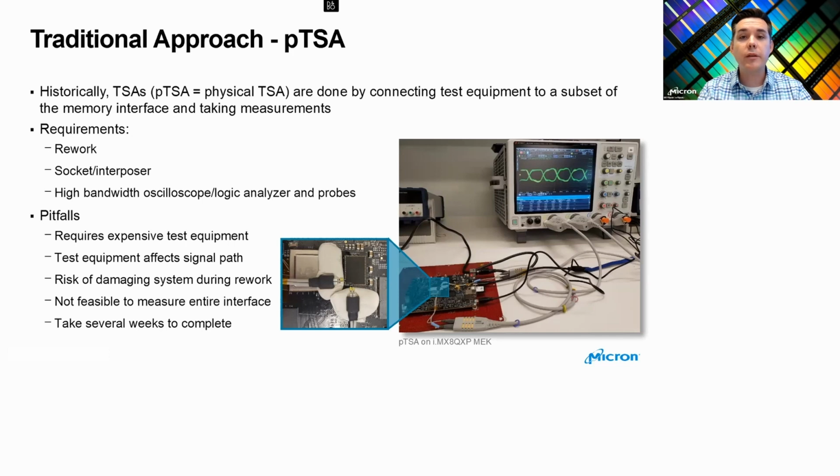This means we connect test equipment up directly to the system and measure the memory interface. In the lower right-hand corner, you can see a picture of a pTSA. There's an oscilloscope connected up to the system. The system in this case is an NXP i.MX 8 Quad-X Plus MEK. And you can see in the zoomed in picture that we've got the LPDDR4 device removed and we stuck an interposer in between the system and that memory device. And then we've got probes connected to some of the pads and we're directly measuring some of those signals.